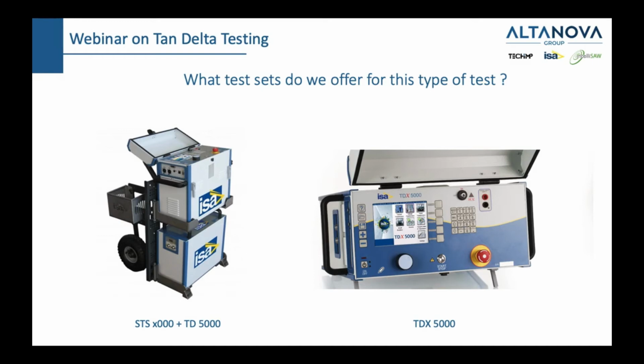Is there a shield between a high voltage and low voltage winding? It will result in a negative value. I have to say I'm not sure if this is so, but if you could send me some ideas, some, let's say, your own experiences to my email, I would be very happy. And we will look into that. The applied voltage must always be sinusoidal. Yes, the applied voltage is always a sine wave.